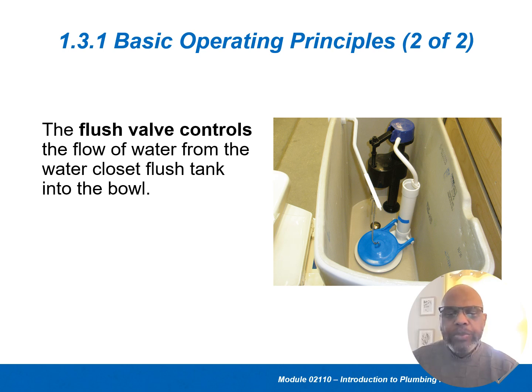So this flap valve is raised up, allowing the water to pour down into the bowl, rinsing off the walls and allowing it to build up a head, and cause it to siphon the water out of the trap. And then it will keep feeding water to fill the bowl back up. So this is basically filling this little tube here, this standpipe, and it actually will continue to add water back to the bowl.